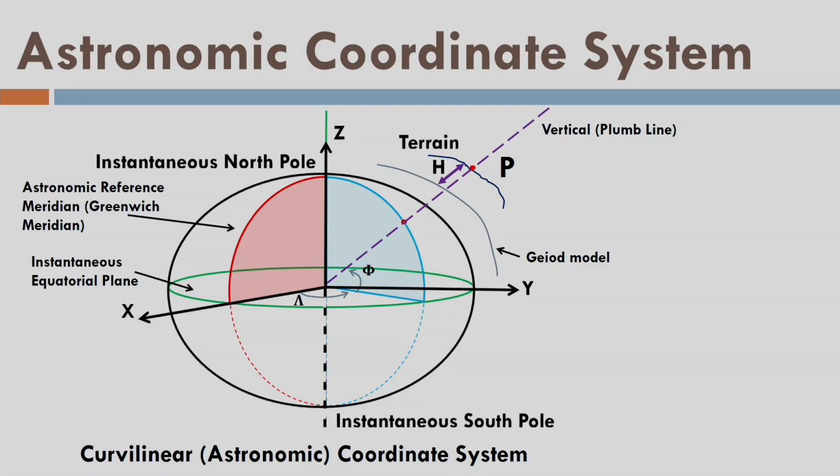Okay, what about the role of the ellipsoid here? So far we did not find any role of the ellipsoid, although we are showing it here for the purpose, and the purpose is that the height between the geoid model and the ellipsoid is called geoidal undulation and represented by Ng. Well, earlier we assumed for a regional ellipsoid that the vertical line and the ellipsoidal normal are parallel, or basically the same, and there was some reason for that, rather it was a limitation to do that. Why?